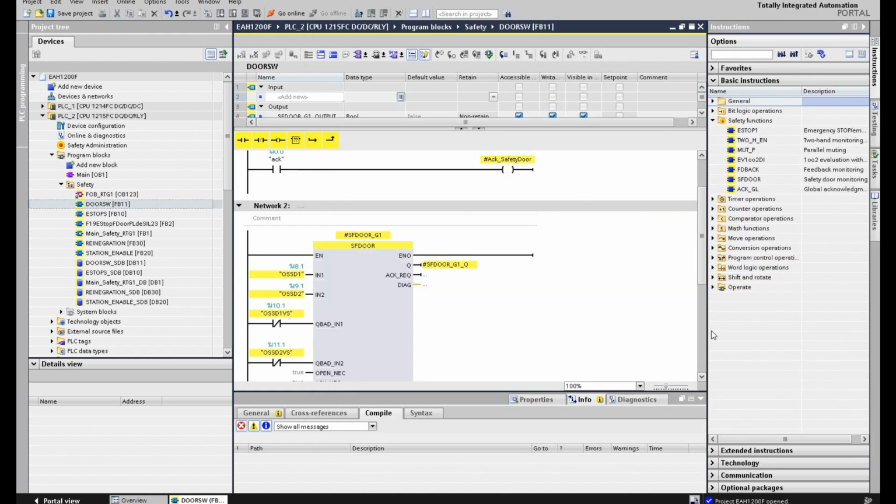And from the function block library, if we quickly go through the safety function blocks, you will find that there's no specific function block named light curtain. However, actually the EStop function block can provide a similar function as the light curtain needs. If we break the light curtain, it gives the signal go off. It's a similar idea as an EStop. So in most cases in the safety controller system, to program the light curtain, most programmers will prefer to use the EStop to connect the light curtain and use the two channels bundled together, and set the discrepancy time on that paired channel. So that is the main idea to program the light curtain.